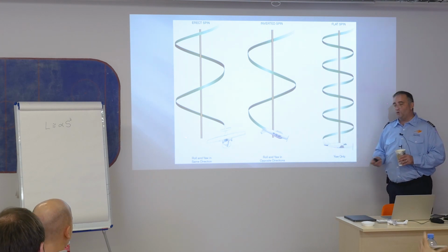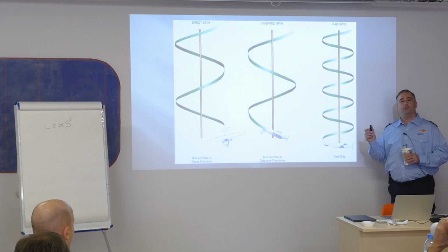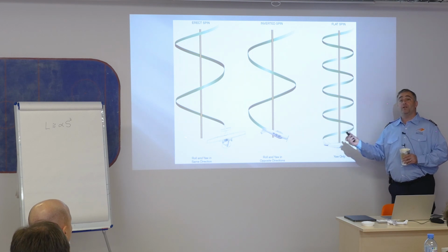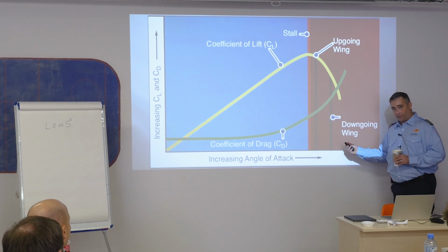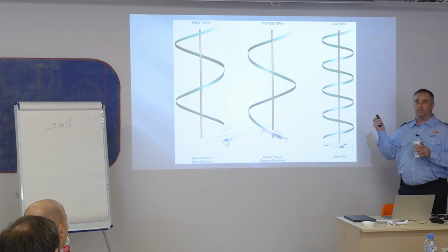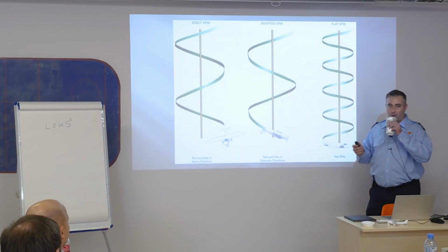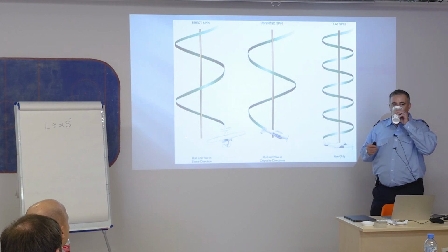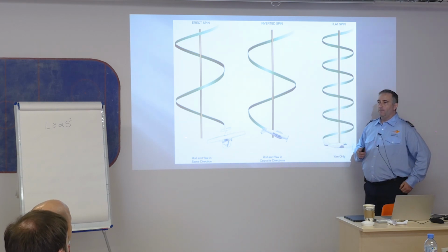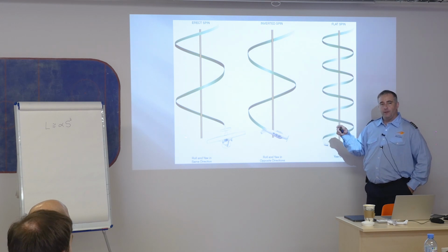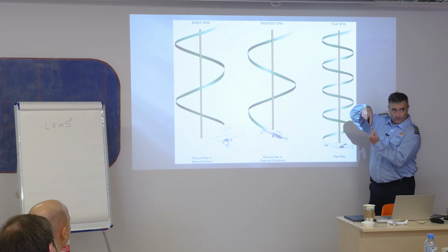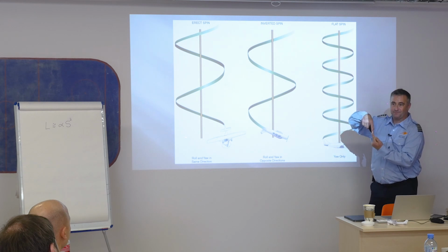But this is a spin. You're not required in your program to intentionally spin the airplane. But the airplane could spin. Again, which one of the wings are stalled? Both wings are stalled. Okay? So what's key to me getting out of this spin? What is the key function for me to recover? I've got to decrease my angle of attack. But where's my flight path? Towards the earth. So where's my relative wind? From here. You can see the challenge.